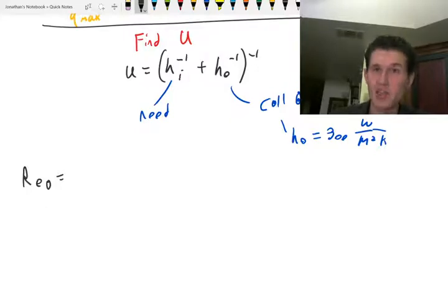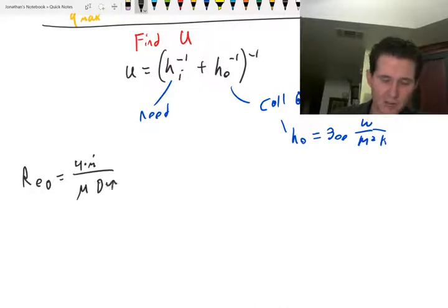Well, near the beginning of chapter 8, you have an equation for the Reynolds number. I would make sure to remember that you have one of those equations. It writes everything in terms of m dot, so it's the mass flow rate. It's just doing algebra for you, but it's really nice. Now, is there anything we need to change for this problem on this Reynolds number? There is. The D is related to cross-section. The diameter is related to cross-section in this equation.